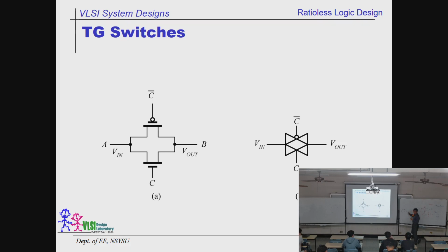So the signal itself can be repeated using even numbers of inverters. And the even number of inverters we call a buffer. A buffer uses a single triangle as its symbol. That means A gets in and A gets out. It's called a buffer as long as they are even numbers. For example, we can add another two to get a long buffer.